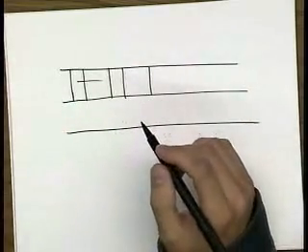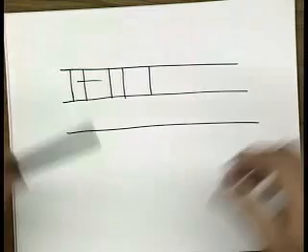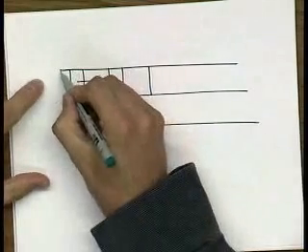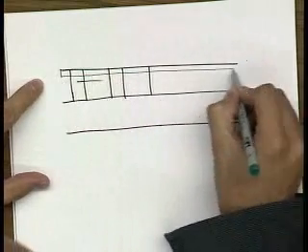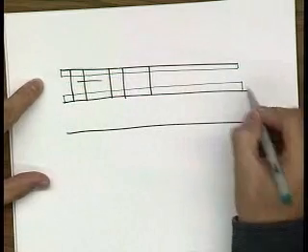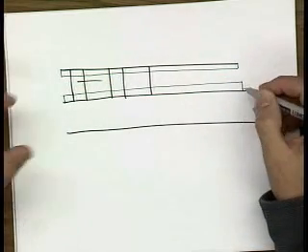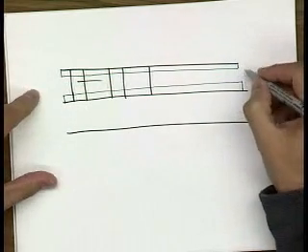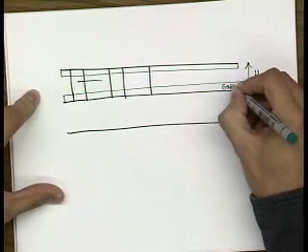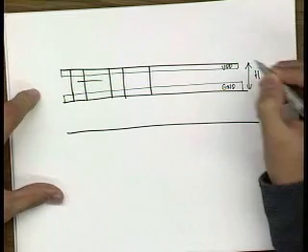Another thing that is also interesting over here is that for the standard cells, we have a convention that VDD and ground go with a certain specified width, and all these cells have the same height. This is, for example, your ground, and then this is your VDD.